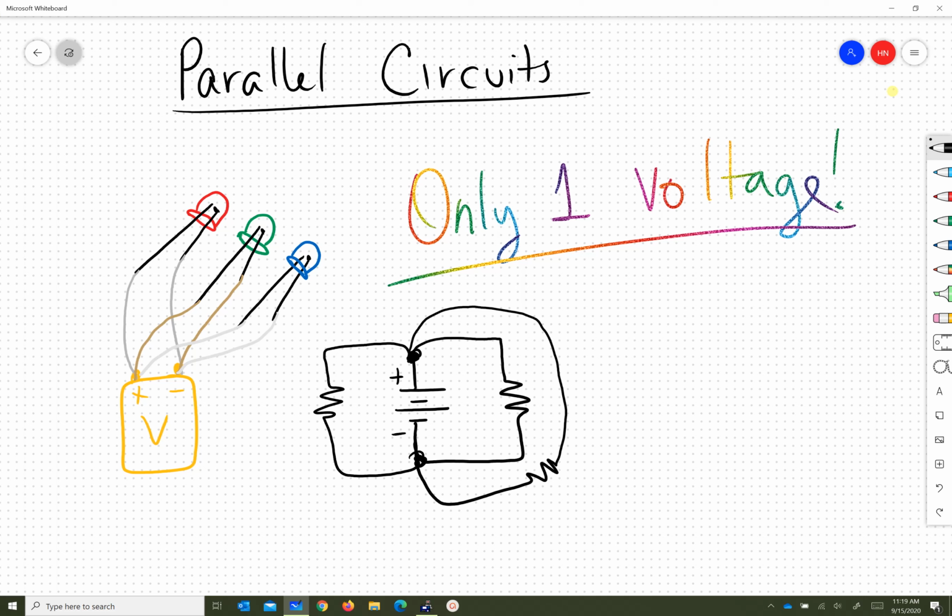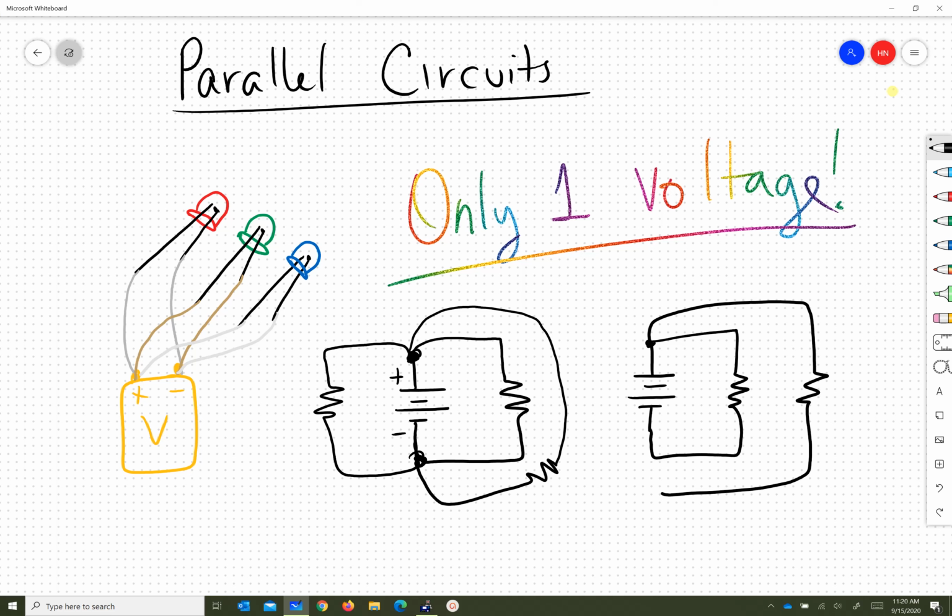So most books, instead of doing it like that, draw the battery. Then they draw one device directly to the right. And then instead of starting from the battery and drawing a device directly to the right of that, they say, well, it's the same place if I were to connect it anywhere along this wire. It's the same connection. So what they do is they connect it at the very end of the wire instead. But it's the same connection.